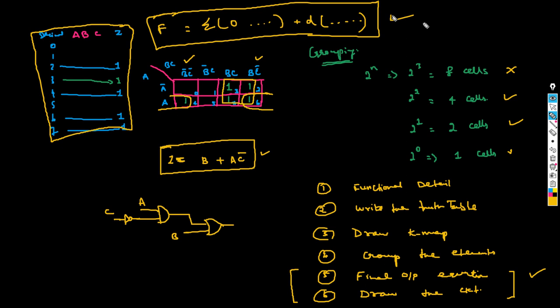Sir, while grouping, we got the prime implicants and essential prime implicants. By grouping only, we can consider it, sir. Okay, so how did I come up with this B? When I group by 4, grouping. That's what we talked about, no? When you group 4 cells, ideally speaking, you have got A bar and A, which is covered in this 4. So that is not going to be valid at all. Now here again, which is common? Only B is common. So that is how we choose it.